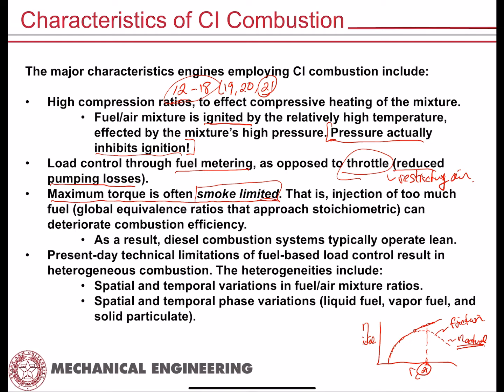For those of you that are really interested in the chemistry, soot is basically a collection of what we call polyaromatic hydrocarbons, okay? And the polyaromatic hydrocarbons are formed through the fragmentation of ordinary hydrocarbons in your fuel that aren't allowed to undergo all those physical processes before the full ignition process takes place, okay?